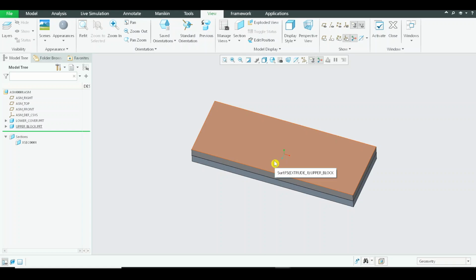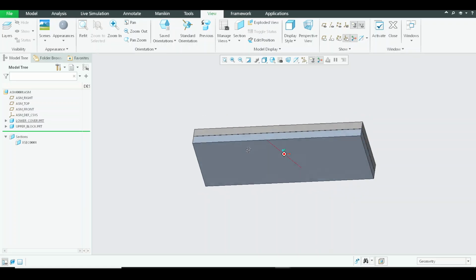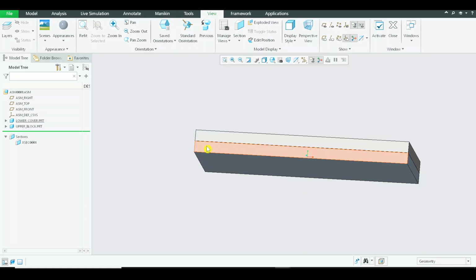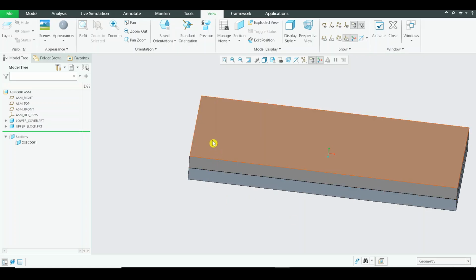You cannot have the buttons over here and also the screws visible. We don't like it, it completely damages the appearance. So we have to insert the screws from the bottom side, and see that it connects to the upper cover. So the first thing is we must have some bosses on the top.